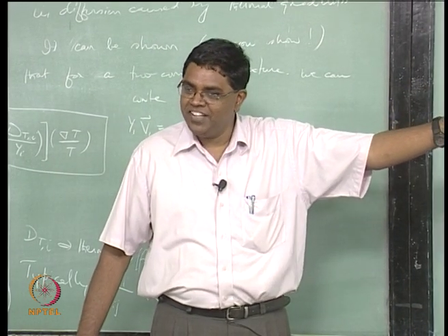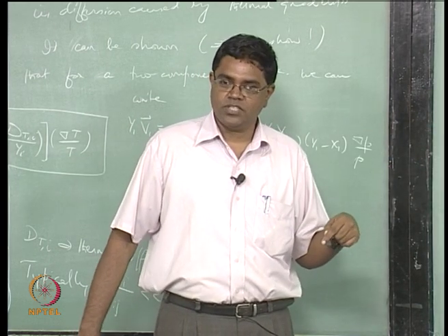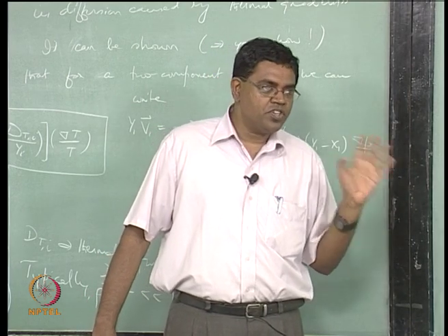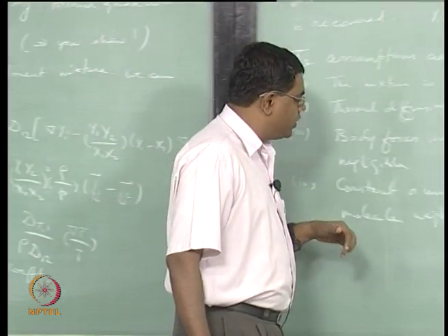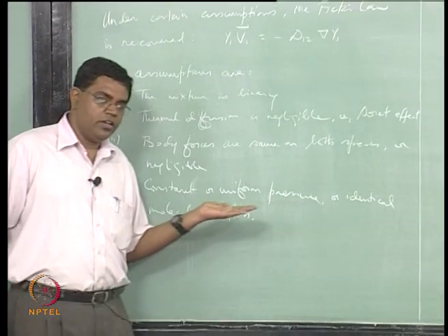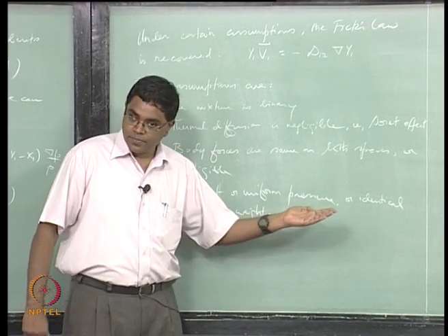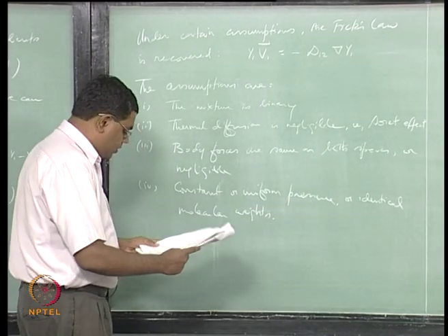It's not slow really, strictly speaking, but the Mach number is low because of the high temperatures involved. Typically we are looking at fairly low subsonic conditions for most of these, and what we will show is that under those conditions it is okay. We will show that the pressure actually becomes more or less constant. Alright, so this is not terrible.